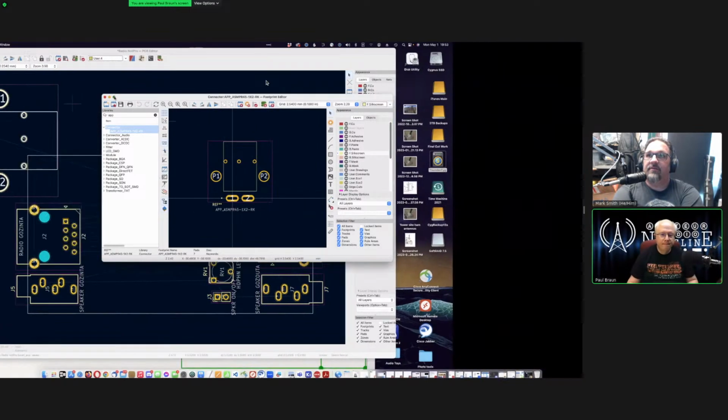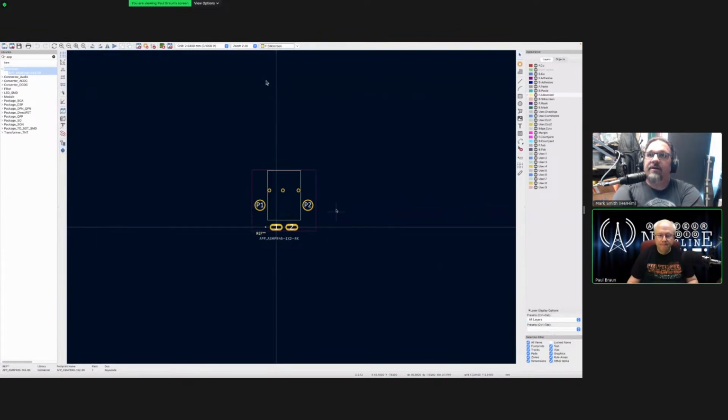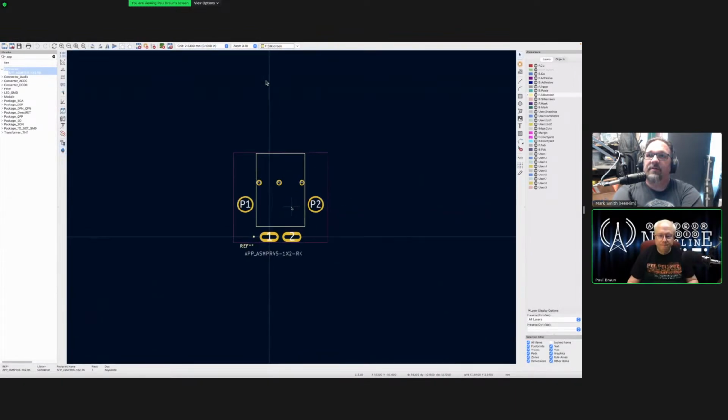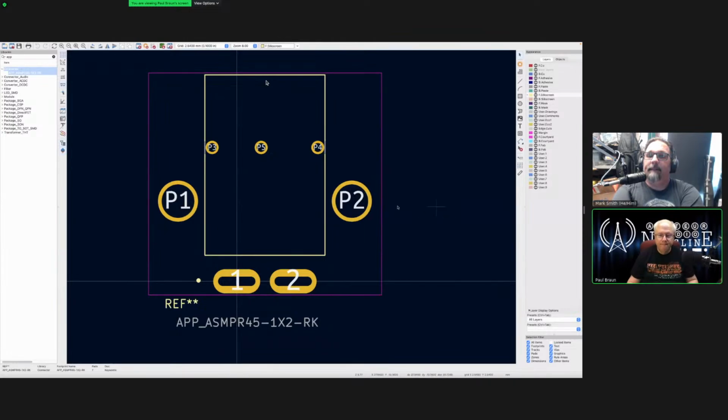Zoom in a bit. Okay. So the first thing I think we want to do is get rid of all of those P pins, all 5 of them. Yep, just select them and delete them. Okay. Select the purple box and shrink it in. Yes, you can grab the...